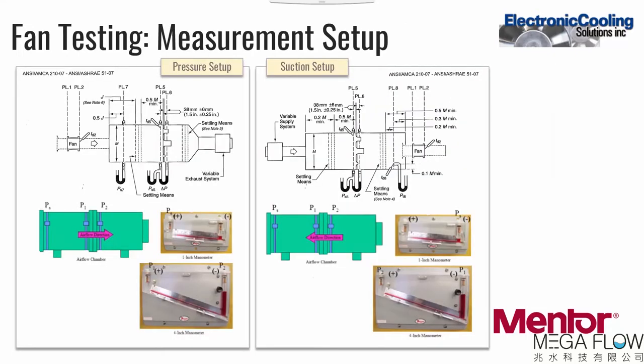The pictures show the schematic of fan test equipment used and configurations for fans blowing into the chamber and sucking air out of the chamber. The chamber has a centrifugal blower to allow variable exhaust. There are settling mesh elements before and after the nozzle plate to make the flow as straight as possible. Pressure at each cross-section is measured by multiple static pressure ports connected by a tube. This averages fluctuations measured at a cross-section. Static pressure is measured at sections shown as PL7. Differential pressure across the nozzle is taken at sections PL5 and PL6.